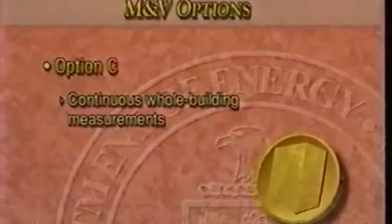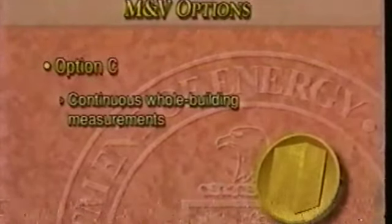Next, option C is geared toward whole building measurement. It can use utility bill analysis or hourly whole building measurements. Now, Brad, would you explain when you would choose option C? Option C is very handy in situations where you have ECMs that you can't measure. Windows, insulation, that kind of thing. Anything having to do with the envelope.